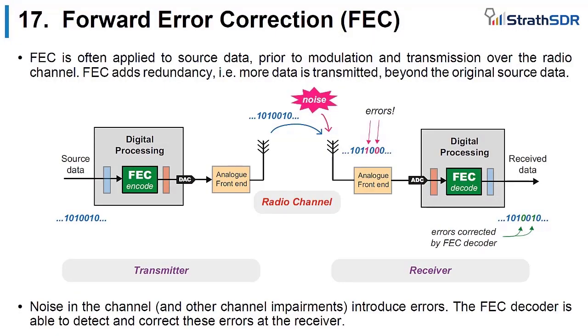In the programmable logic, there's also forward error correction. If you're familiar with communications, you'll be aware that very often we add redundancy to the symbols of data we transmit, and this can be used for error correction. At the receiver, that's a very intensive computation process. So rather than use processing cycles for that, what we have in the RFSoC are some SD-FEC blocks, hardware-coded blocks to accelerate maybe turbo coding or LDPC coding, and again make the architecture as efficient as possible when you're working with radio implementations.